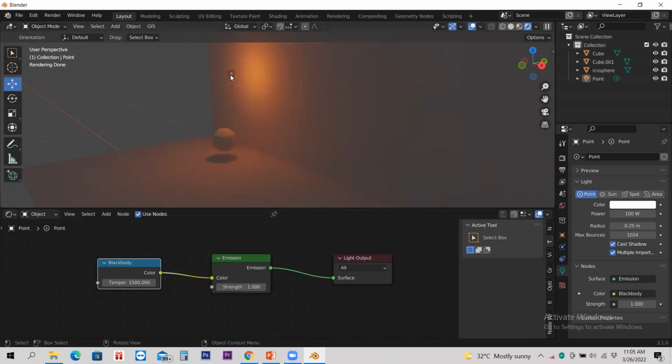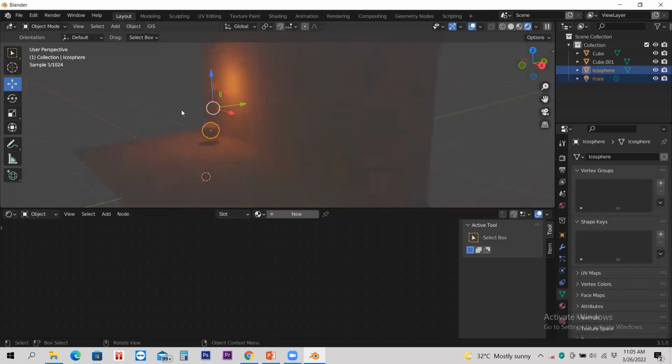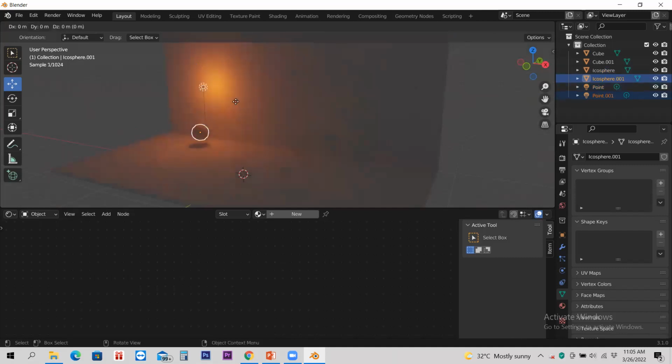Then what I'm going to do is I will select this light fitting and this object. I will copy one time, because then I can see different colors. To copy, I press Shift D. Then I'm going to give the direction. I think it is Y direction. No, it's X direction. I'll press X. We'll move it a little bit here. Place it here.